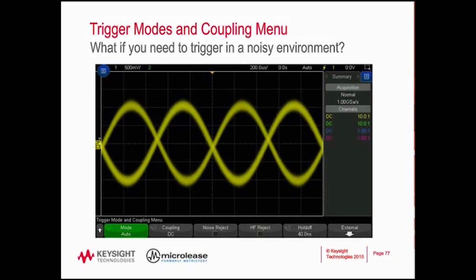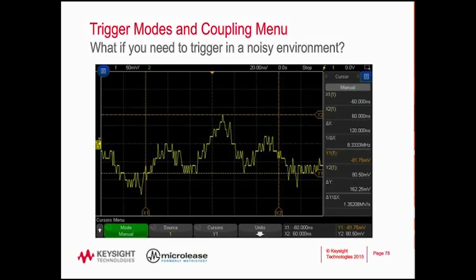And basically what we're seeing is the rising edges of the noise that are riding on top of the falling edge of the signal are large enough to trigger the oscilloscope. So when we're telling it to trigger only on rising edges of the signal, it's actually capturing rising edges on the falling edge as well, and we can prove that by zooming in. So I did a single shot on a falling edge, and we can see there's actually a 160 or so millivolt rising edge riding on top of the falling edge.